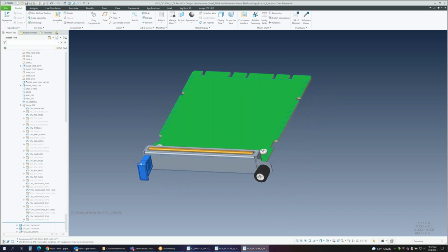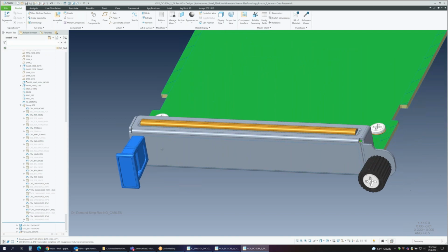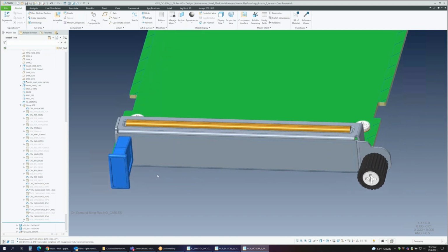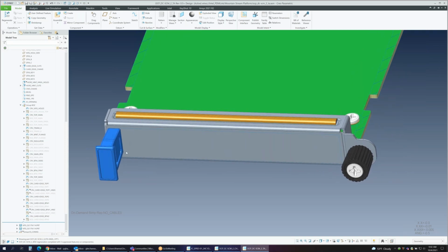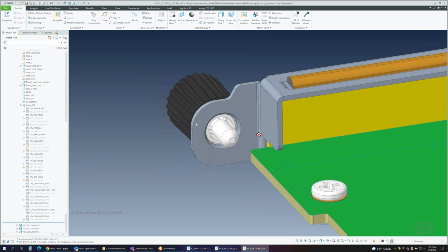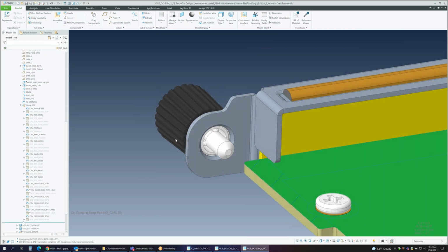A few other things. We looked at the handle on the bracket and said that would be optional. Normally, mechanically, you would want something to pull instead of a screw, but due to the amount of components, connectors and real estate people have on this card, the committee thought it better to make this optional. If you want to use this style as opposed to the internal locking, you can either have the handle or not. The other thing is the custom thumb screw that's on the OCP NIC. We look to leverage that as well.